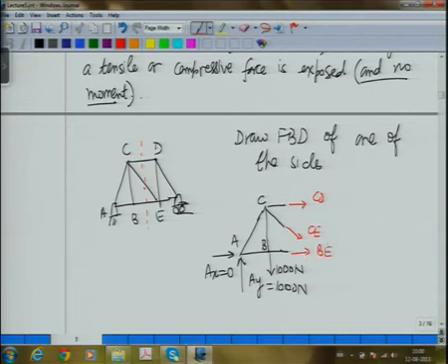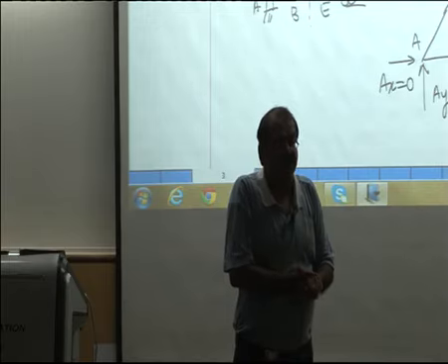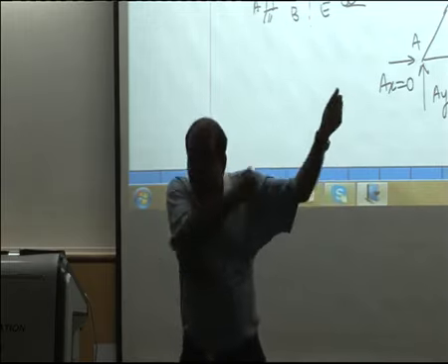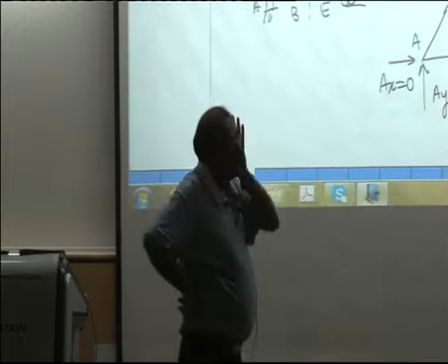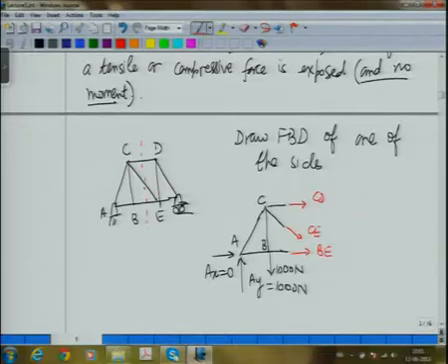So at the cut, I have these three forces, a force in the direction of CD, a force in the direction of CE, a force in BE. And all these, as I have shown, they are tensile forces. Because at the cut section, if the force is tensile, it will come out like this, it will pull the member. So all these three have been shown to be tensile forces. These are all three unknown forces.